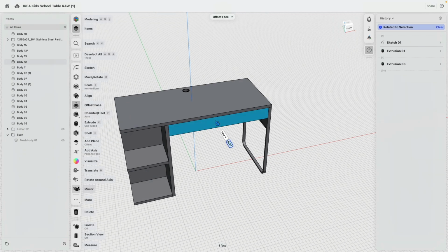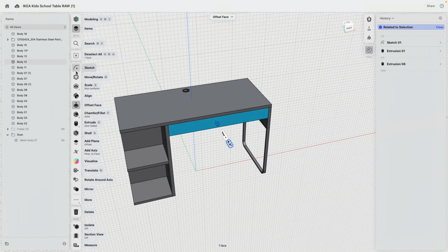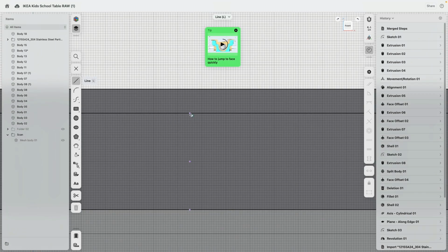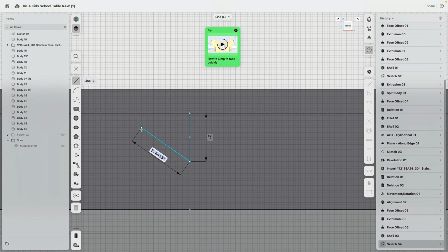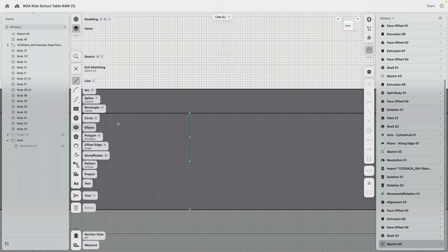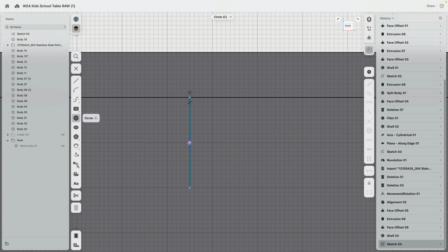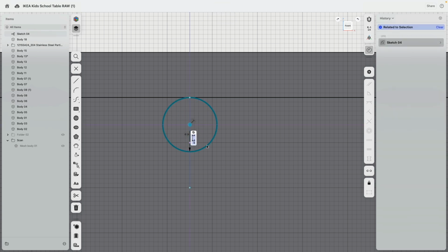Unisolate. And here, let's add actually an opening. We use the same idea, kind of like with the circle on top. So here's a vertical line, midpoint to center point. There's a circle. Be careful with the midpoint. There is the circle. There we are. Let's say 1 inch. That's good for a finger.